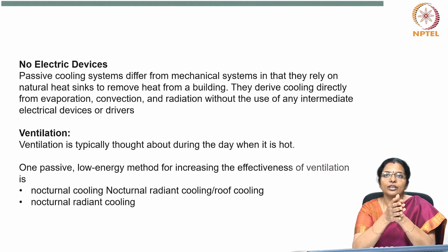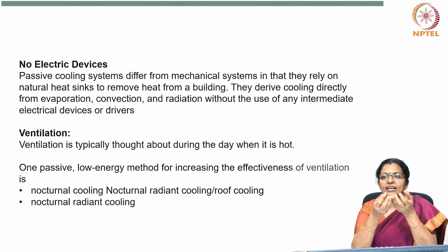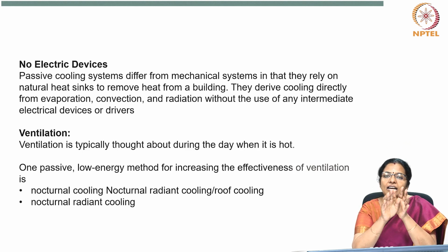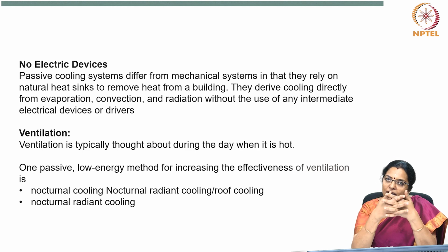How can this be done during the day? During the day, you can spray the roof with some water, and this begins to radiate interior building heat to the atmosphere much earlier in the evening than an uncooled roof. This technique has been typically used by our forefathers.